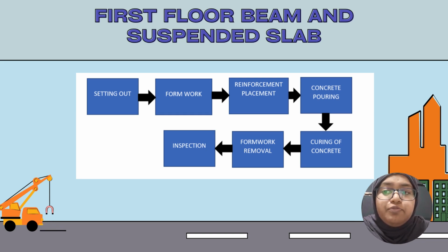After the formwork removal, check for surface damage, cracks and deflection. And the last one is we need to ensure that everything is level and aligned.